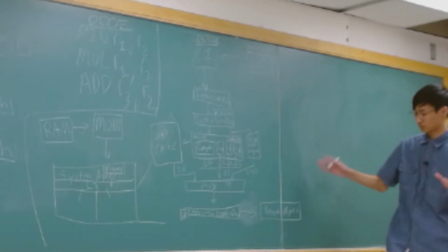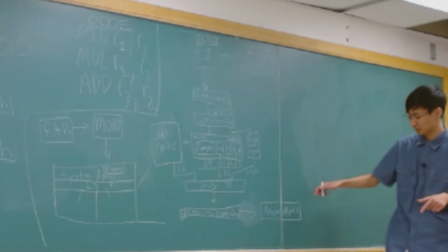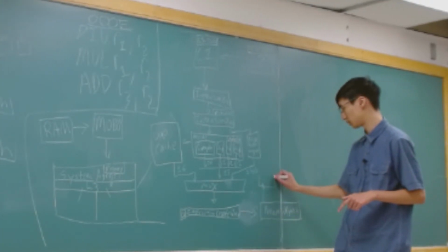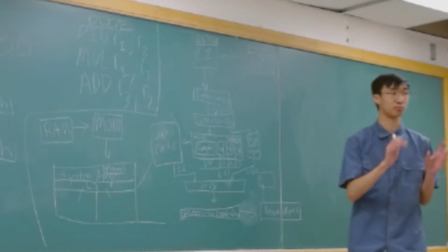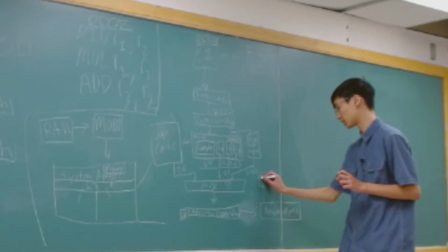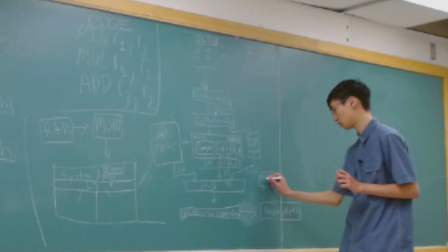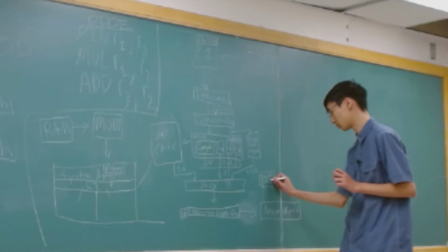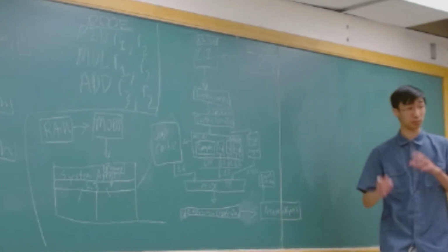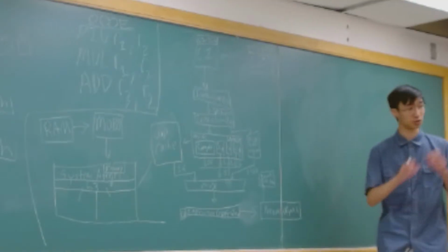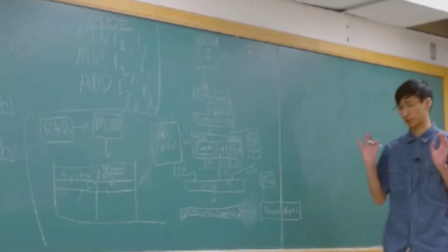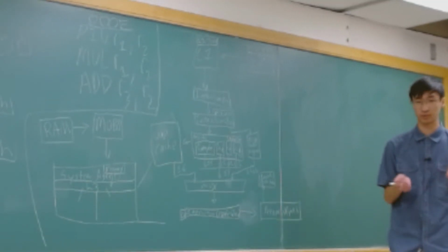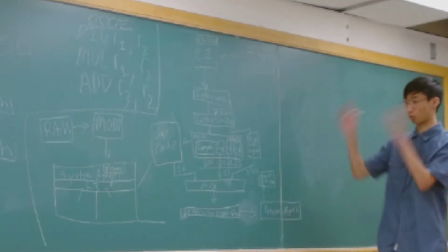And this is the part that really gets messy, because we're going to push instructions or snapshots into what we call a branch order buffer. This branch order buffer will be used later, as you will see, to roll back CPU state if we ever make a mistake. For example, if there's an exception, right? So if you throw a floating point exception, you can roll back state or something like that.